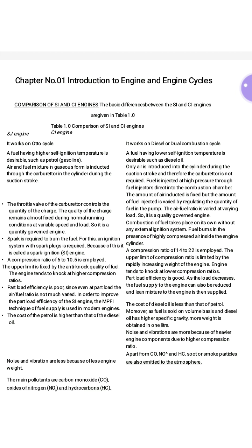During suction, when the piston moves from TDC to BDC, negative pressure is produced inside the cylinder, and due to that the air plus fuel mixture is sucked in. In a CI engine, that is a diesel engine, only air is induced during the suction stroke, and therefore the carburetor is not required. In an SI engine, a carburetor is required for the mixture of charge.